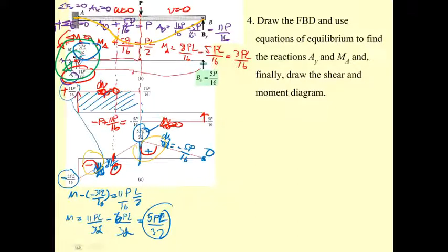Since the beam has this kind of shape, when you consider this, you're going to reinforce this beam upward, and this one you're going to put in the lower portion. That means the reinforcement of this beam, if this beam is an RC beam, the main reinforcement is going to be like this. Extra main reinforcement on the top, and the bottom.